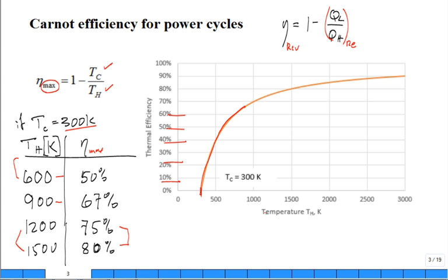Often you have to reduce the temperature at which it's burning because it creates a lot of NOx. It gives you emissions problems, or you have to reduce the temperature because of metallurgical considerations, the equipment can't handle the high temperatures. But in the combustion, you can go to very high temperatures. But if you go to a renewable or alternative energy source, it may be that people want to use, let's say, a 400 Kelvin heat source. That's water boiling temperature, roughly a little over 100 degrees C. That's pretty hot. Hey, I should be able to make a lot of energy out of that.